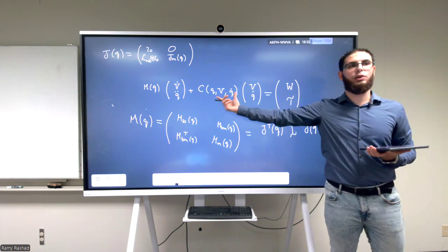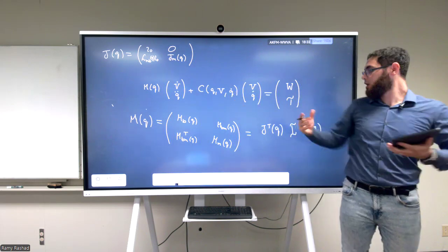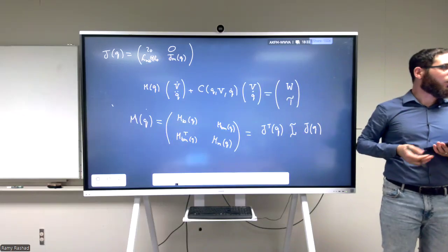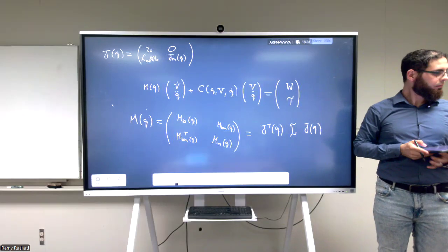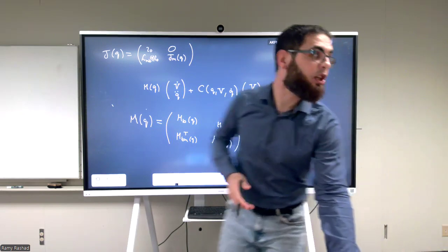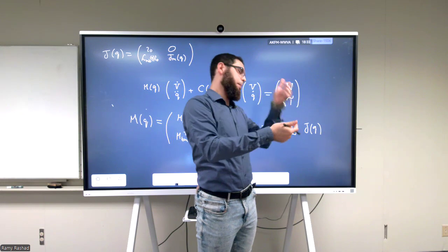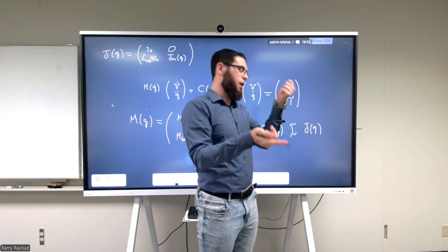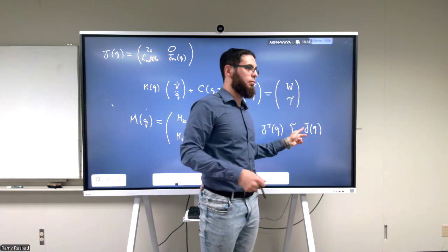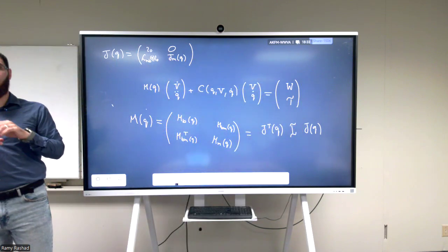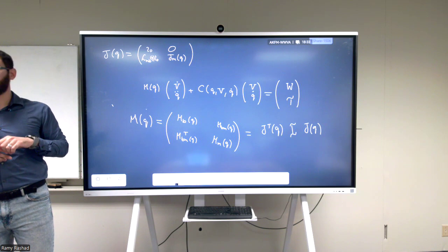You can do exactly the same for the C. You can get a closed form solution for all of the inertias, the adjoint, and so on, exactly in the same way that we did for a fixed base manipulator. You can generalize it. The I here is generalized inertias. So this will have the inertia of the base in the base frame, the inertia of 1 in the 1 frame, up to n in the n frame. We just added everything by 6. We just add 1 row in all of the expressions that we have.